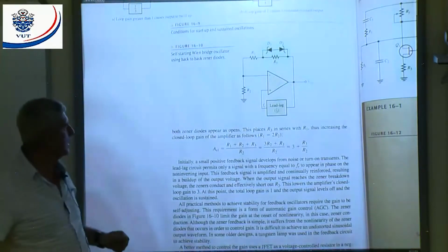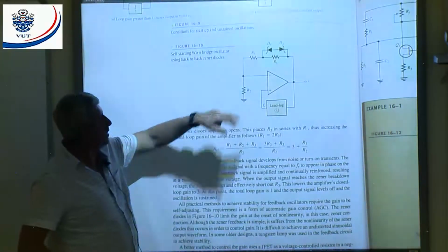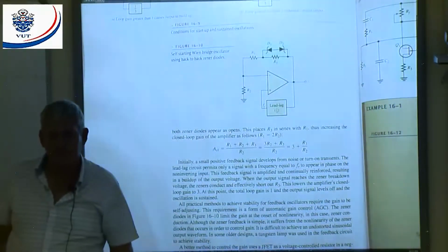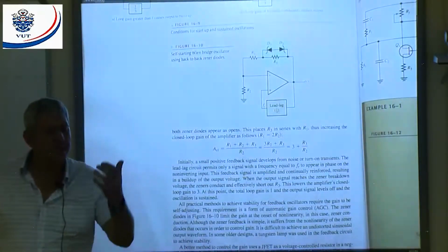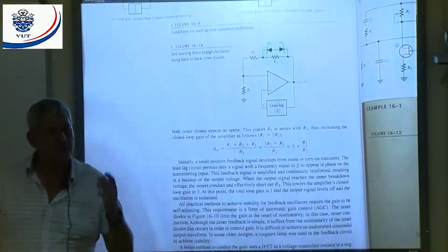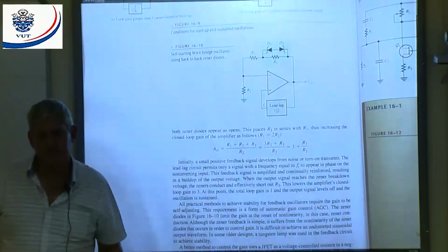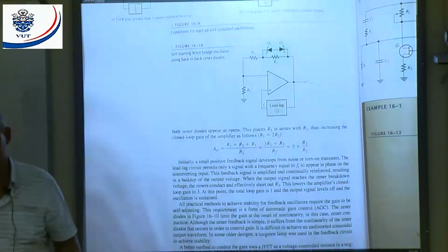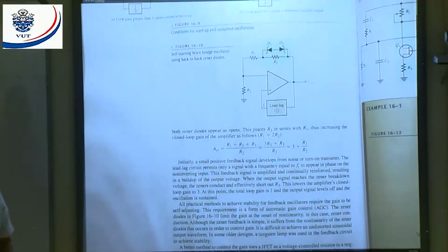Now what will determine my gain then? Only R1 and R2, all right. You with me? That means now my gain will decrease to 1. Exactly 1, or the closed loop gain should be equal to 1. You with me? Must I repeat again?